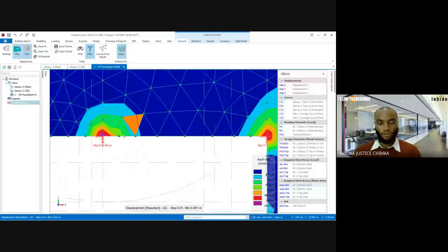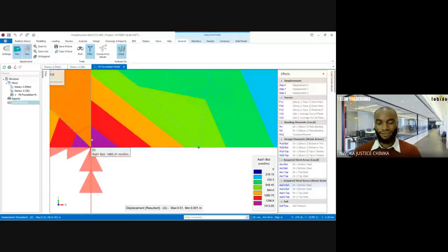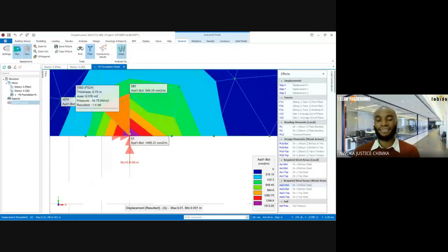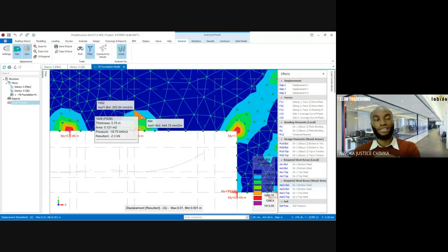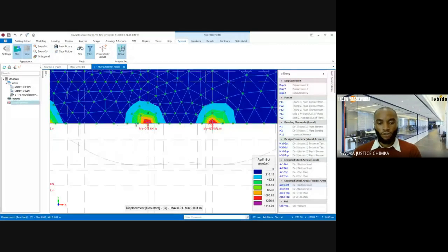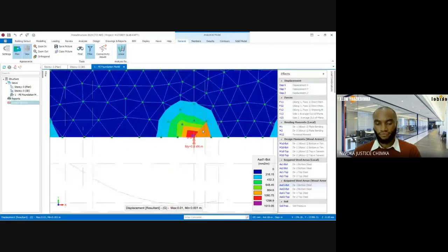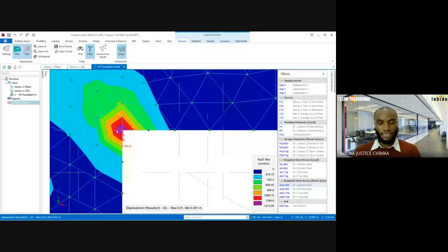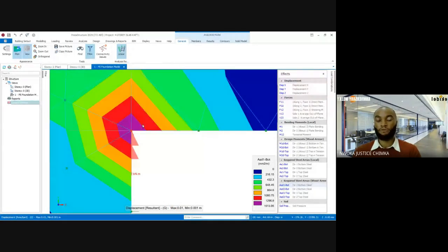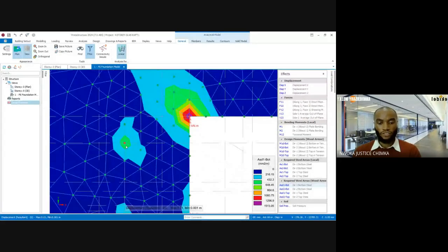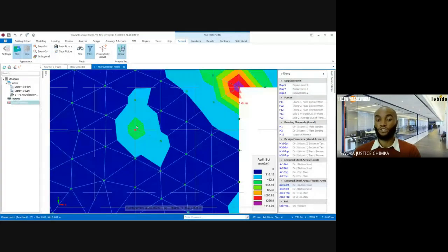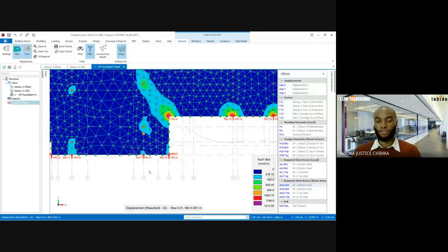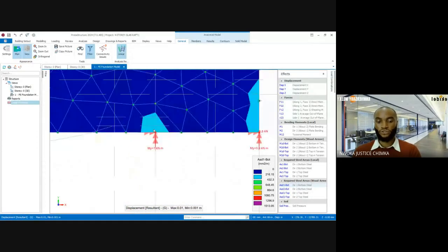Again, you need to check that too. You can see that it's always hiding inside the column, because that's where the punching occurs a lot. If you also check this other column here too, you also see that. Then there's a column here too. You can see that purple. This column doesn't have it, because maybe it's not carrying much load, so that doesn't require punching. Then this one too doesn't have it.